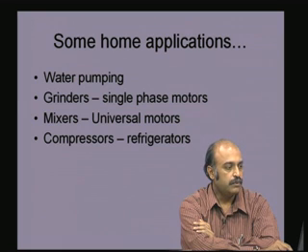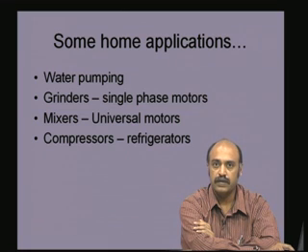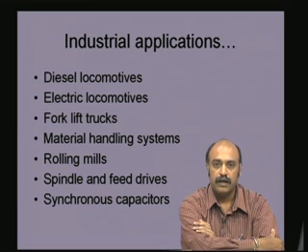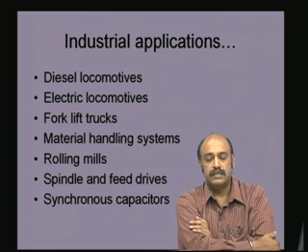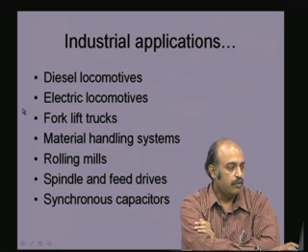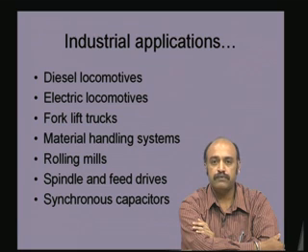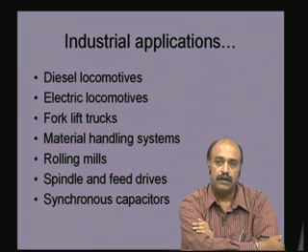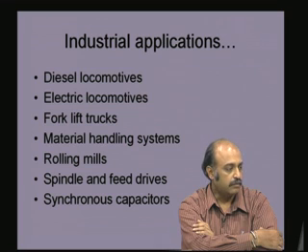Therefore, we need to study the basic electrical technology, at least the first level, then later on, depending on interest, advanced level courses. You also have several industrial applications where electrical technology is very useful and probably becomes a must in many cases. Diesel locomotives, where the diesel engine is connected to a shaft which will drive an electrical generator like an alternator, the output of which is converted into DC, and then again an inverter and motor to drive all those things.